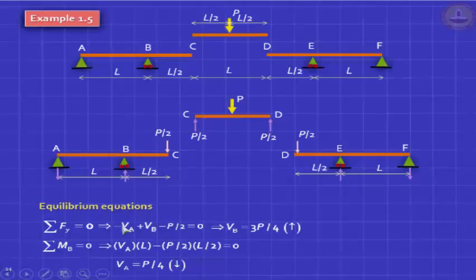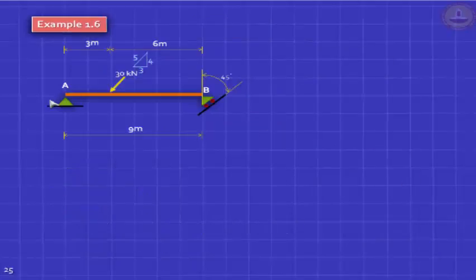So the direction is important, which means in detailing, you must make sure this doesn't ever lift up. Normally we put rubber bearings, but it will lift up. So you have to have a bearing which holds it down. Very important. Okay. So whatever you get symmetrically, you will get that. These are your answers. Right.